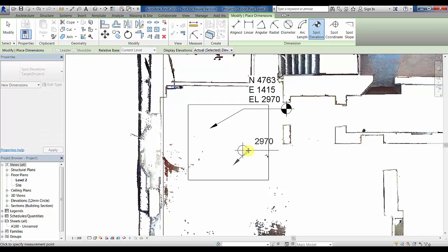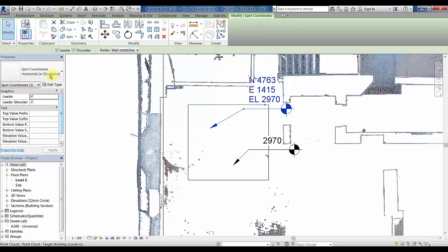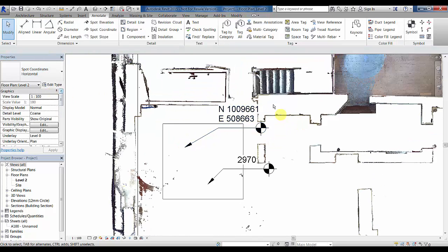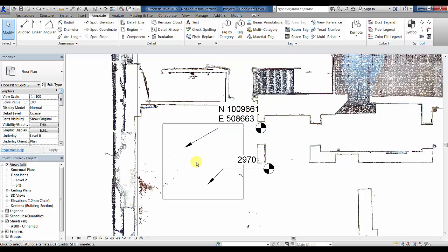One note of caution using this method is that it is geared towards surveyors producing measured surveys as a deliverable and who like to be able to give real-world spot heights, etc. It is quite possible that your customer is going to link your file with others later down the line and therefore may not want to deal with these large coordinate systems so far away from the origin of the shared coordinate system. So it's probably best to check with the end user prior to embarking on a survey.